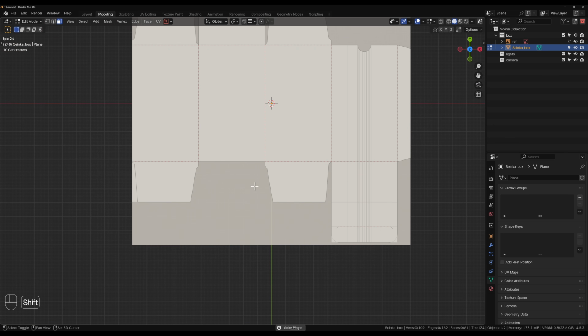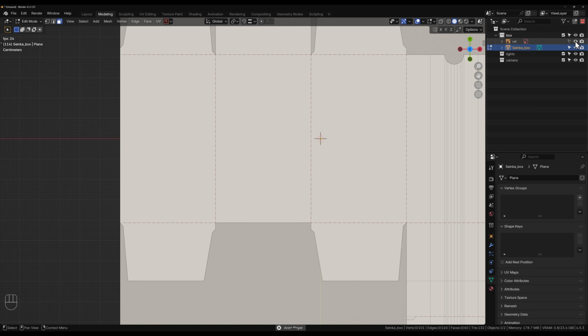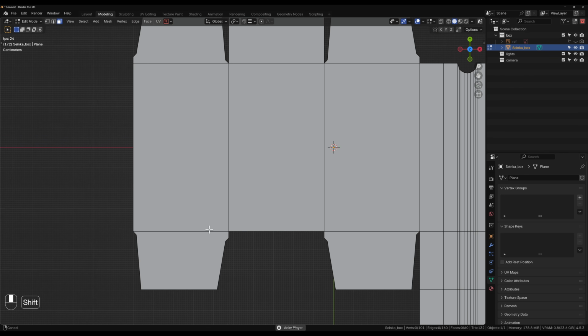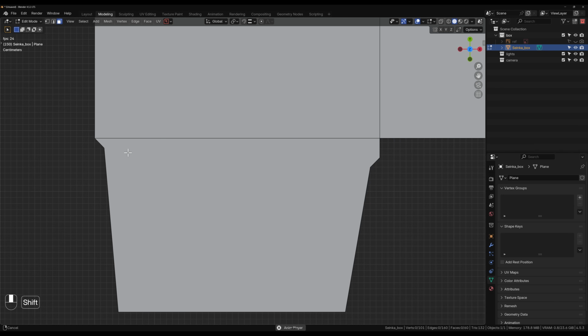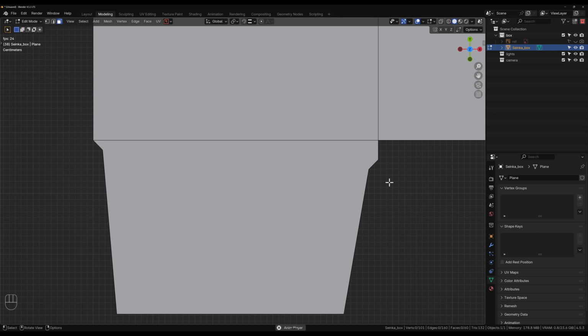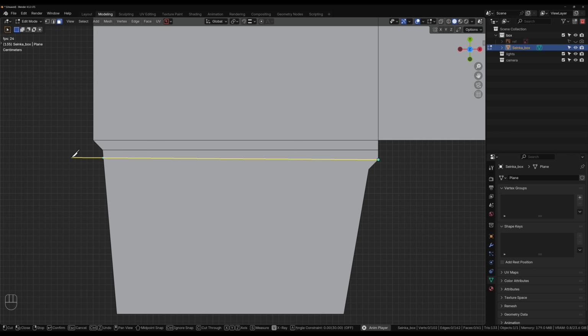Faces. Now what I'm going to do with the knife tool is I'm going to hide my reference here. And I'm going to actually turn everything back into good topology. So all I'm going to do is go K. And I should explain what's going on here. So we click, snap it to the vertice here. As we go along here, I just want to press A. And that will snap to a 45-degree angle. And then I can click straight through and it will send a cut through there.